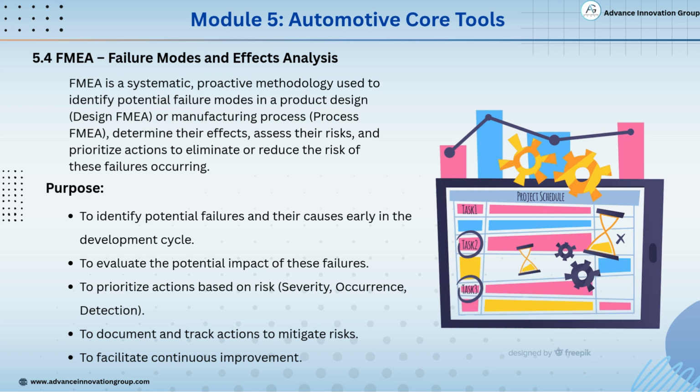Purpose of FMEA includes identifying potential failures early in the development cycle, evaluating the impact of these failures, prioritizing actions based on risk, using criteria like severity, occurrence, and detection, often abbreviated as SOD, documenting and tracking risk mitigation actions, supporting continuous improvement efforts. Think of it like a structured way of asking, what could go wrong? How bad would it be? And how can we prevent it?